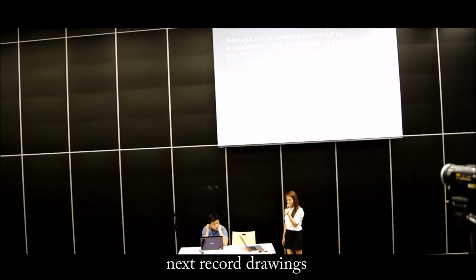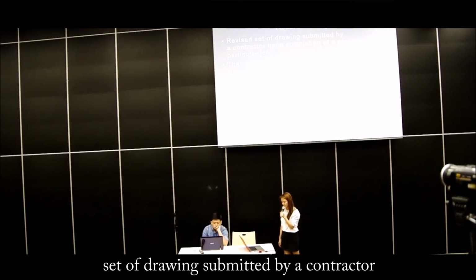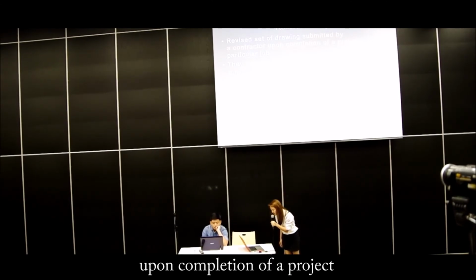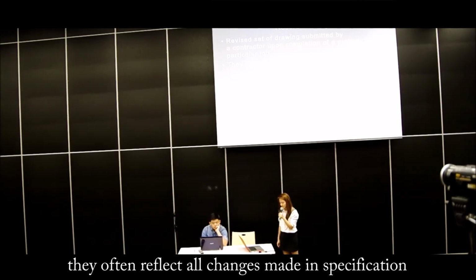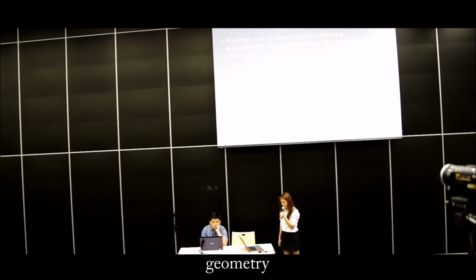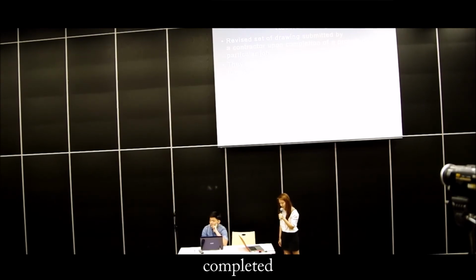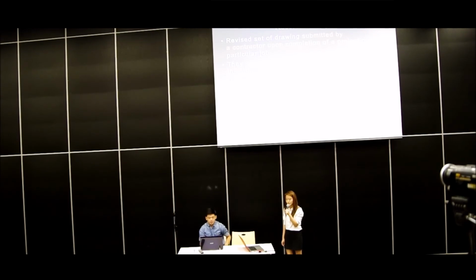Next, record drawings. Record drawing is a set of drawings submitted by a contractor upon completion of a project. They often reflect all changes made in specification, which usually show the exact dimensions, geometry, and location of all elements of the work completed. Record drawings are also known as as-built drawings.